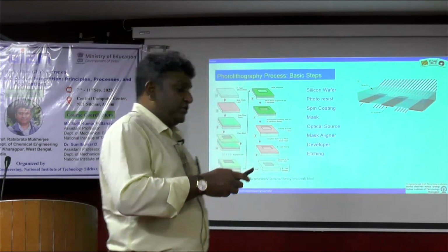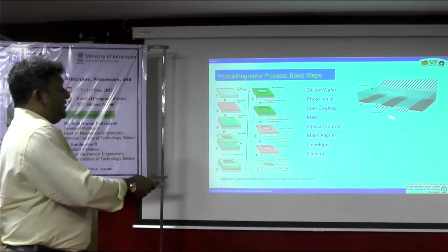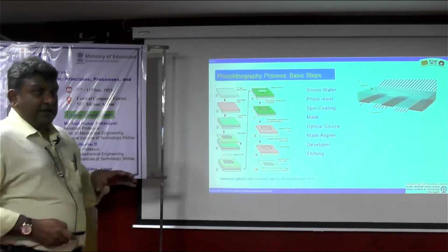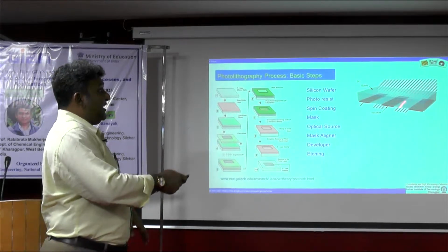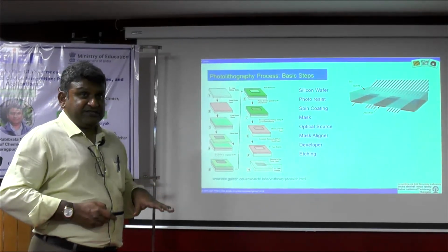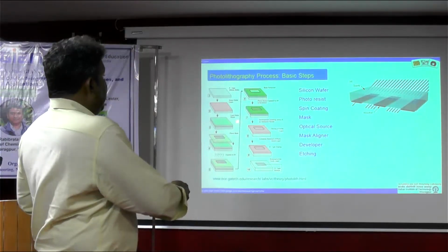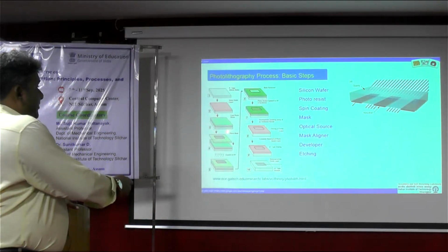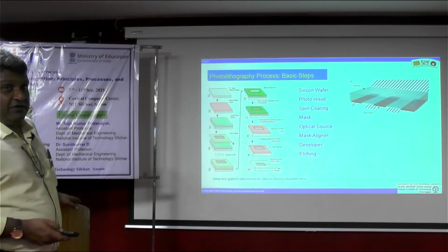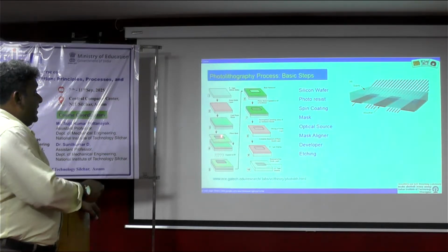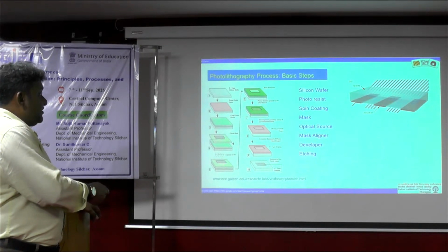And basically, what you do is you have some hardware element called a mask, which selectively allows the light to pass at certain locations, and at certain locations it does not allow the light to pass. You basically take a photoresist layer. Generally, if you are fabricating a device, it's on silicon or oxide-coated silicon. Place the mask and then expose it to light.